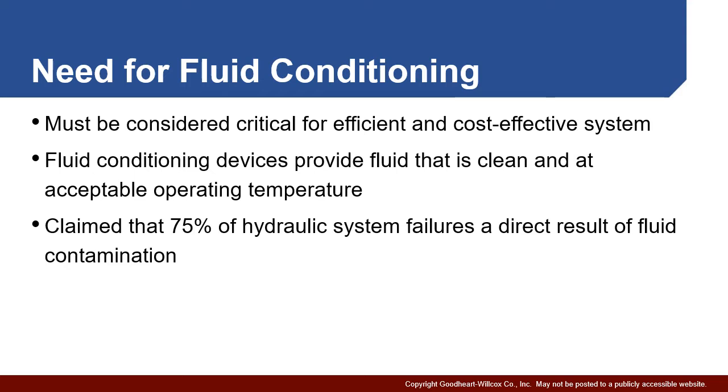Essentially what we're trying to get them to do is make sure they maintain the fluid at the right level of cleanliness, keeping contamination out of it, and at an acceptable operating temperature, making sure it doesn't get too cold, too hot, etc. It turns out that studies have shown that about 75% of all the failures in hydraulic systems are actually directly related to contamination.